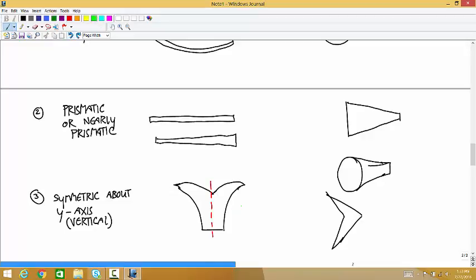And let me draw, let's say that this is the bending axis. This is the bending axis. So we can do calculations for this one, not this one. If the bending axis were vertical on this second cross-section, then we could do it, because we'd have the proper relationship between the axis of symmetry and the bending axis.